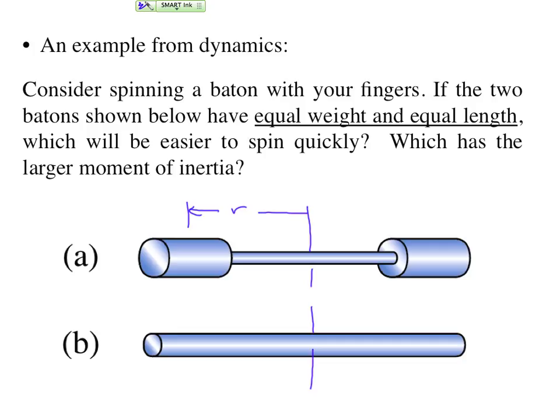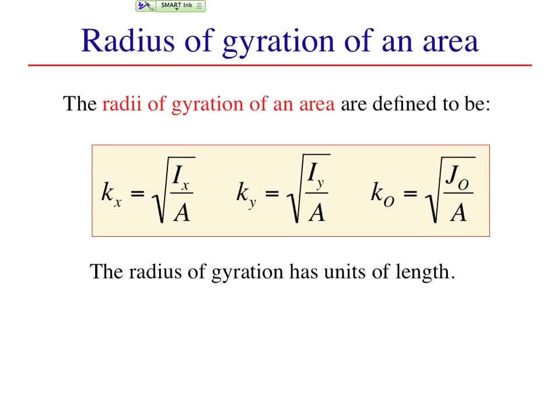We define a quantity called a radius of gyration to denote a kind of average position for defining an effective area or mass moment. Again, the language of this phrase seems quite foreign, so we can rearrange the expression a bit to make it look more familiar. In this case, we could write k sub x squared equals the area moment with its functional form explicitly shown divided by the area.